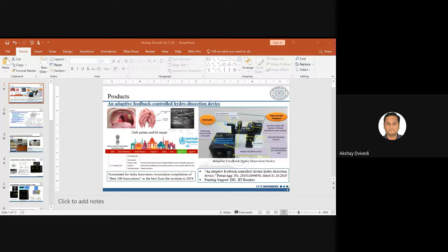You keep a dielectric medium, which is basically a liquid, one example is kerosene, between the tool and work. And here, you provide potential difference. As you go on working with the process, there will be sparks coming into action, and those sparks will create temperatures again in the order of 8,000 to 12,000 degrees centigrade, similar to what was happening during laser machining. Now, we used this same process, reconfigured it in a way where it can serve our purpose of tool roughening.